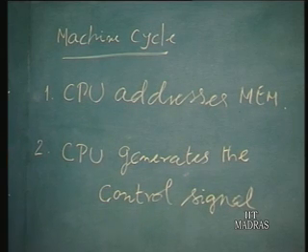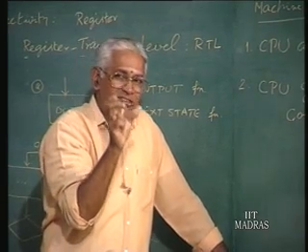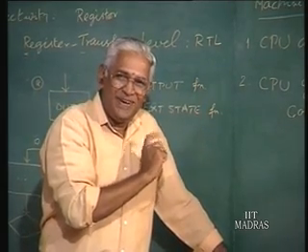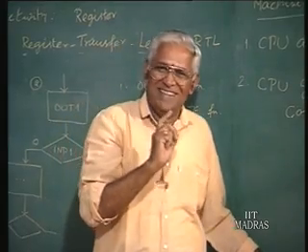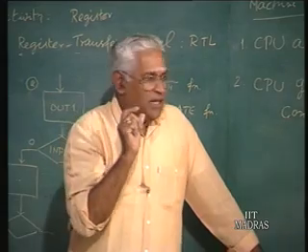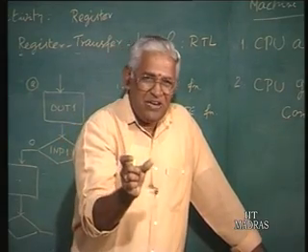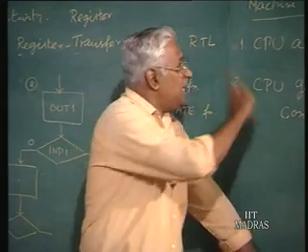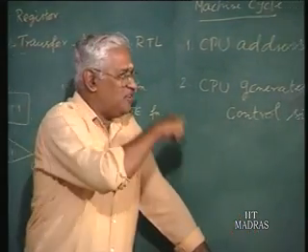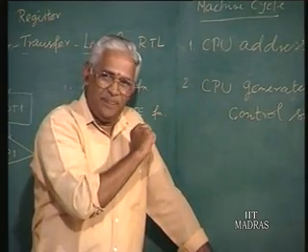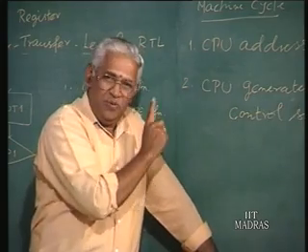With reference to the CPU, we talk about the instruction word which is coming over the bus as data. Now remember, I was telling you once, when I say data, don't confuse program constructs, instruction and data. From the memory point of view, whatever is stored is a piece of data, some unit of data. Now in the instruction fetch, the memory must respond with the instruction word, which comes as data over the bus, which the CPU will read.